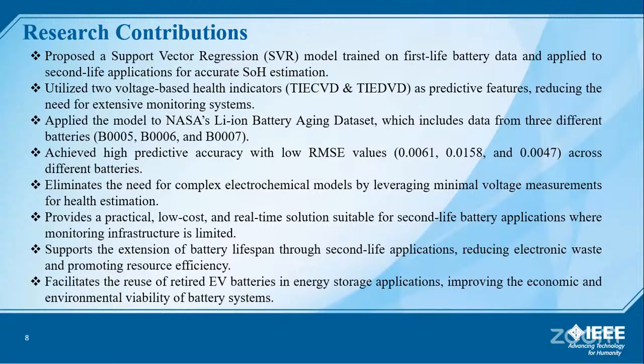Research contribution. The key contributions of our study include the development of an SVR model trained on the first life battery data and applied to second life applications. The introduction of voltage-based health indicators, the TIECD and the TIEDVD, for state of health estimation. The application of our model to NASA's battery aging dataset for validation, achieving high predictive accuracy with low RMSE and MAE values across the different battery datasets, providing a practical, low cost and real-time solution for second life battery applications, extending battery lifespan and reducing electronic waste.